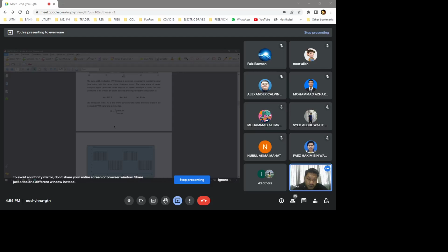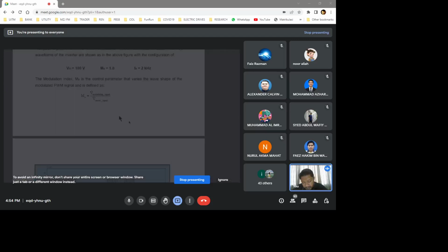The circuit operation is always the same. Whenever switch 1 is on, the output will connect to the positive of the input voltage. If the bottom group is switched on, or the bottom switch will be on, you're going to have a negative across your output. Yeah, positive, negative. So this is the output. And again, remember, this is a square waveform, this is an AC waveform.